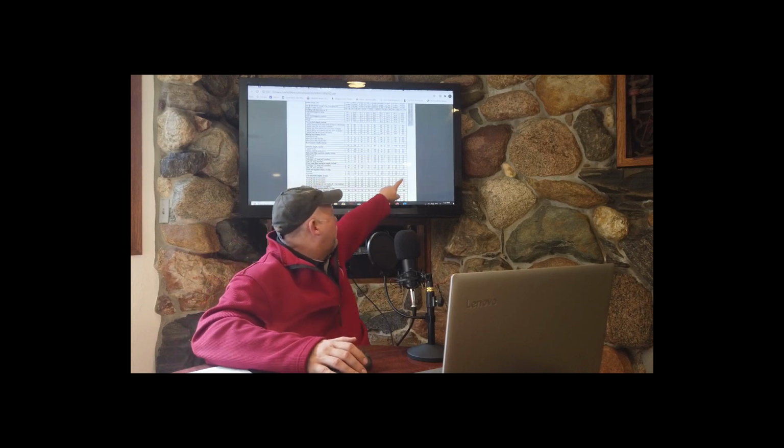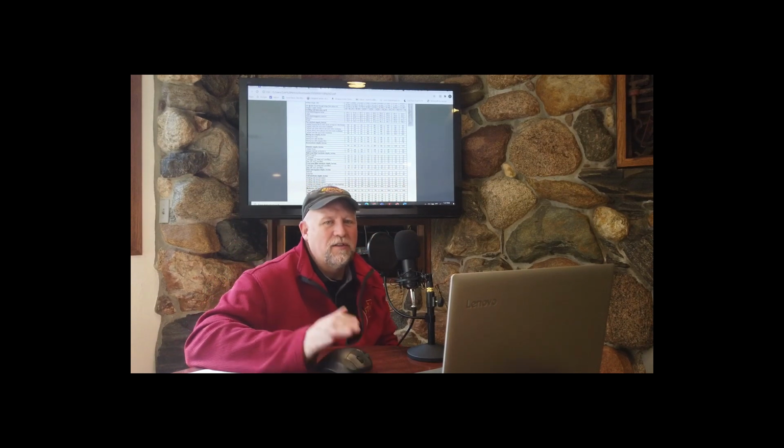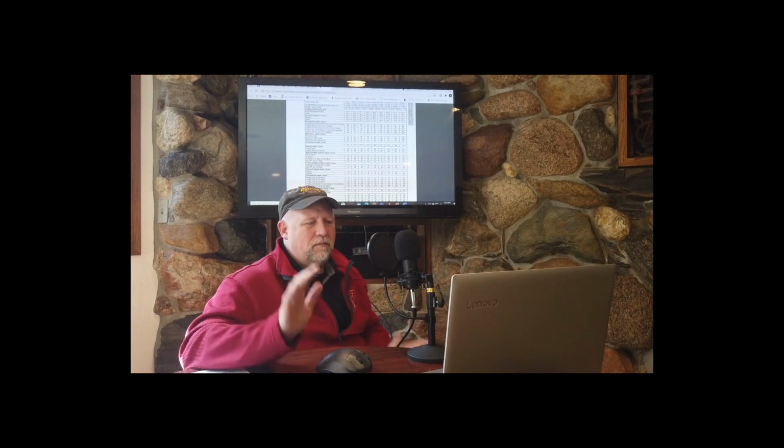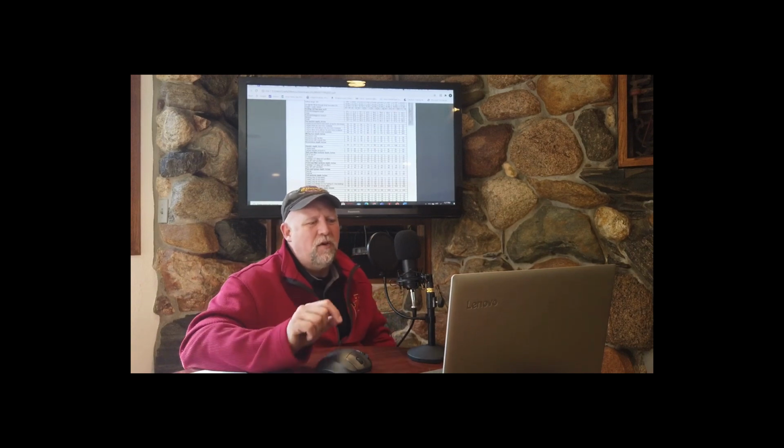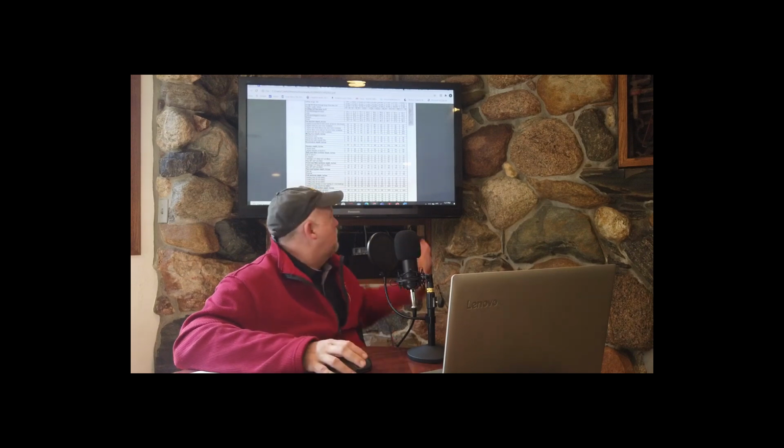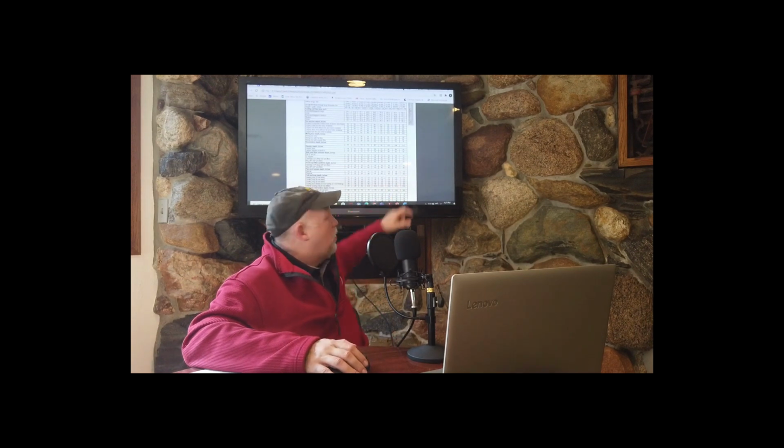Heating only, 2-row water, 12 inches deep. That's it. That's our only choice. It's going to be 12 inches deep. And the reason is that we can get about any temperature range that we want off of a 2-row heating coil using boiler water. So we don't need a whole lot of options.